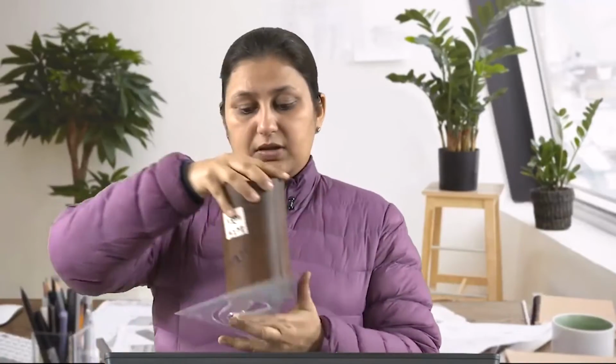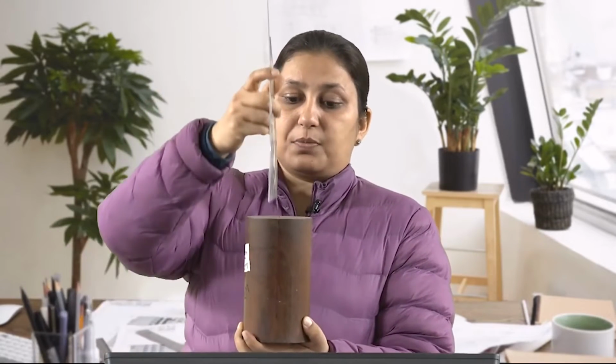Now, before we go on to understand the section of these different types of solids, we also have to understand there are multiple positions of section planes. So, we can assume that the section plane is perpendicular to both the reference planes. So, it will be cutting. For example, we have this solid. If we have this solid kept, assuming there is a vertical plane here and a horizontal plane here, this section plane could be perpendicular to both the planes. In this case, we will be seeing the true shape in the side view.